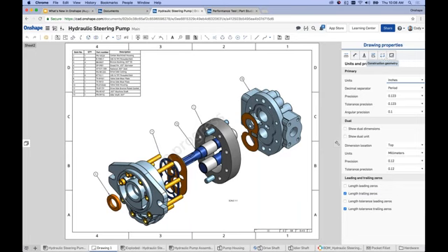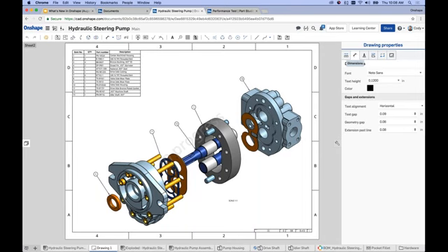So you're going to have properties for things like units of precision, but also for dimensions. If you wanted to change the height or the font of dimensions separately from annotations, for instance, you can now do that, right? Here's font, height, color options that are specific to dimensions. I think that's the important thing to stress, as well as the typical dimension options, right? Things like gap and alignment and so on. So that's the dimensions tab within the drawing properties flyout.